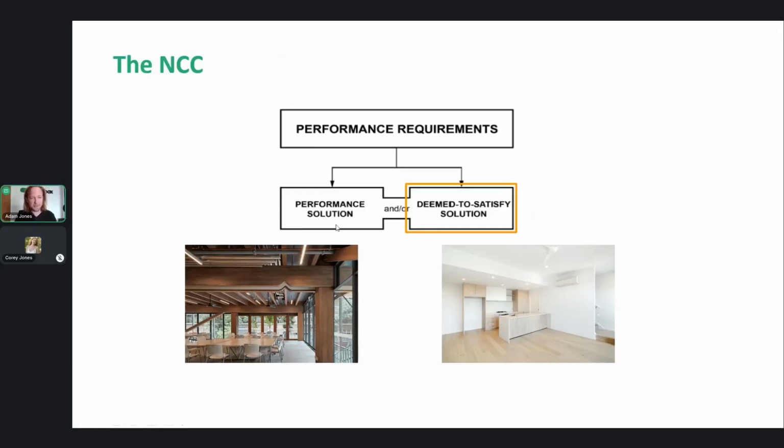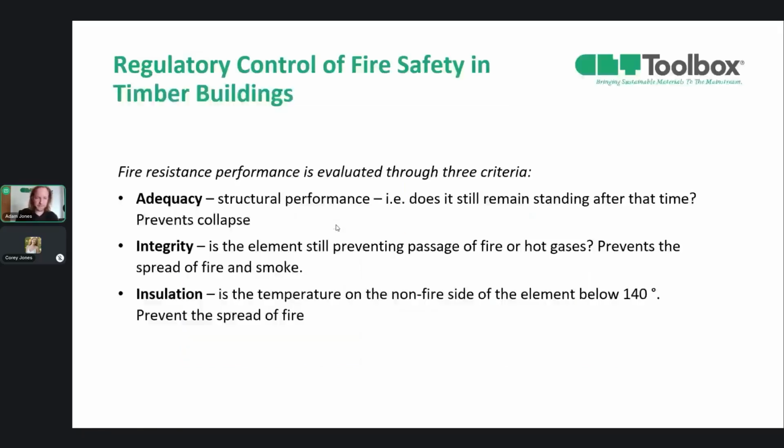And that way you can actually achieve more flexibility in the outcomes, particularly when it comes to exposed timber. So there's three different things. Performance requirements can be met by, and the typical way of justifying how you can achieve the requirements, there's three definitions that occur. One is structural adequacy. That is related to structural performance. Does it remain structurally intact for the certain time period that you're trying to chase there?